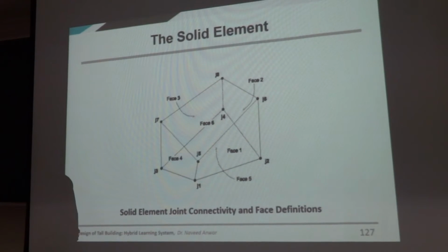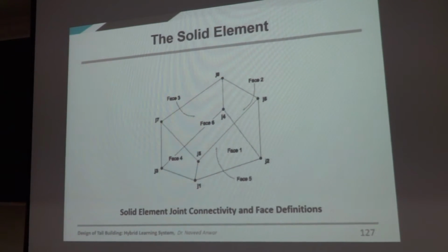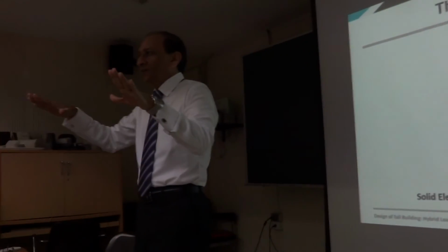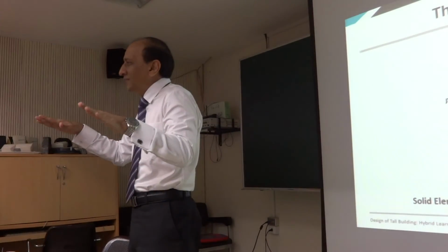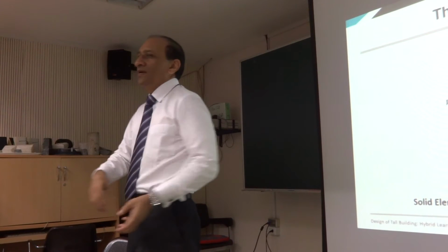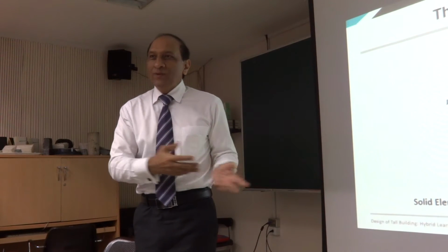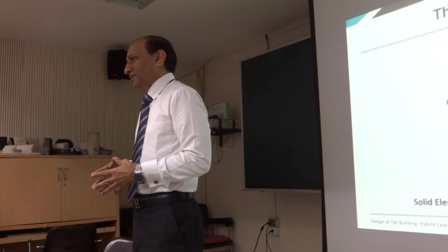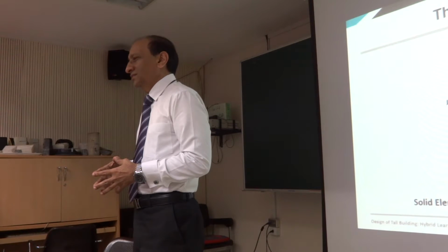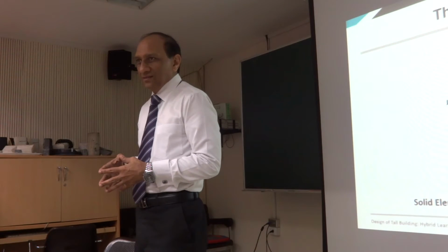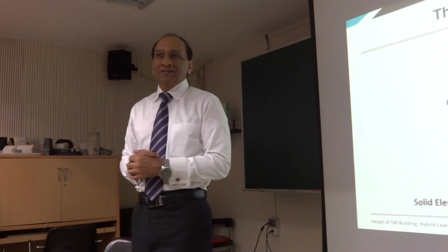I tried to explain to you. Line element, physical modeling is very little, so properties have to be more. Two-dimensional physical modeling is more complete, dimensional properties become less. Here the physical modeling is complete, geometric properties 0. Right? No geometric properties needed, only material properties are needed.